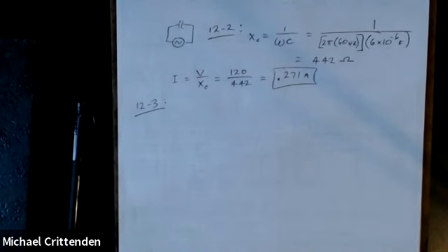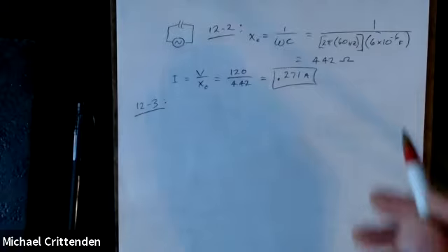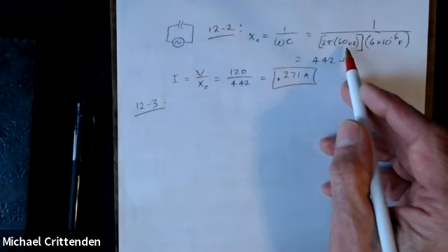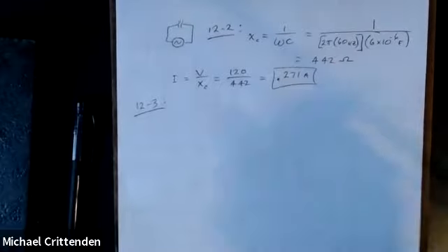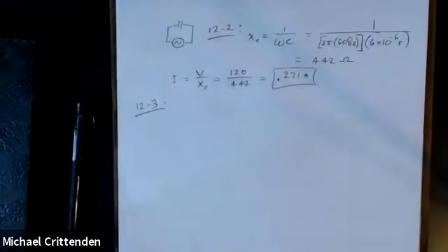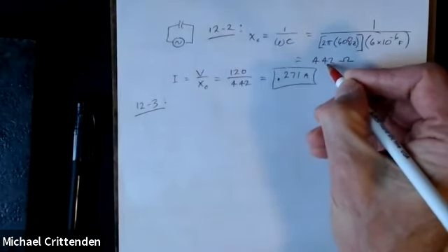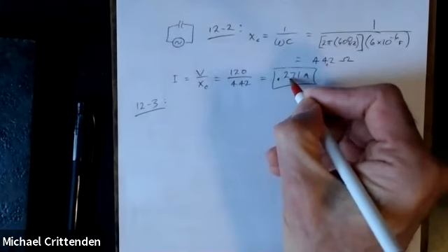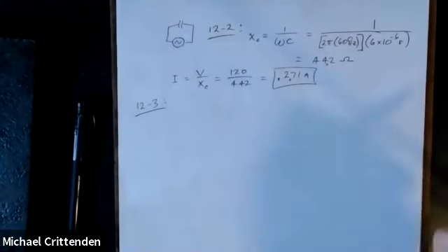Either kind of reactance, XL or XC, on the other hand, is a function of the frequency. So if you have some way to turn up the frequency, I'm not even going to bother to write all of this out again. I just got a different color pen here. And I'm just going to put another 0 there on the frequency, which means the decimal point gets moved over to there, which means the decimal point gets moved over to there.